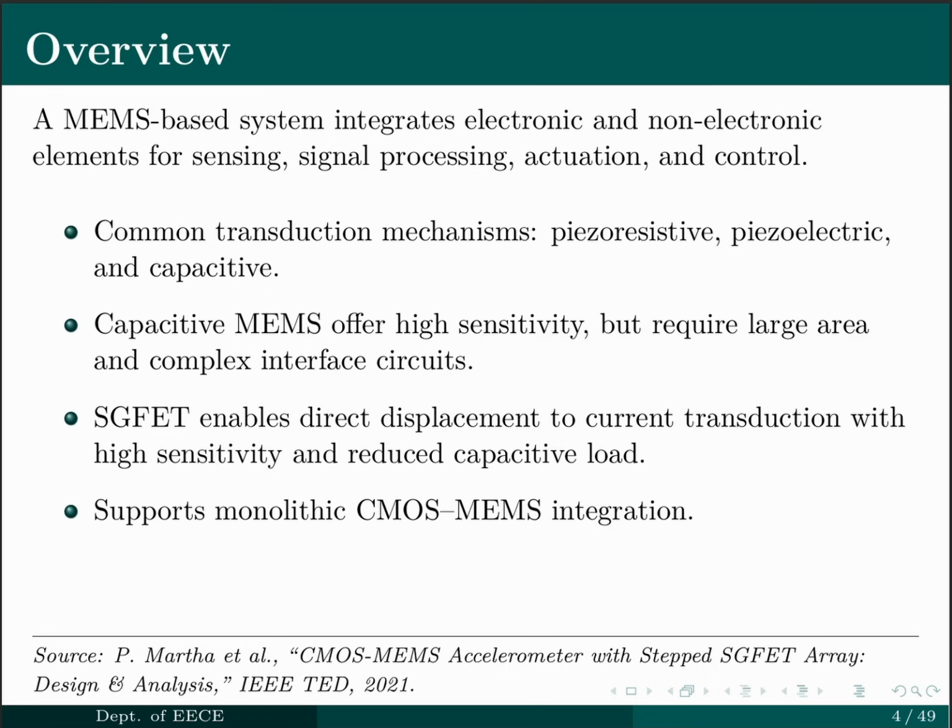To overcome these problems, SGFET is the alternative, which enables direct displacement to current transduction with high sensitivity and reduced capacitive load, and it also supports monolithic CMOS MEMS integration.